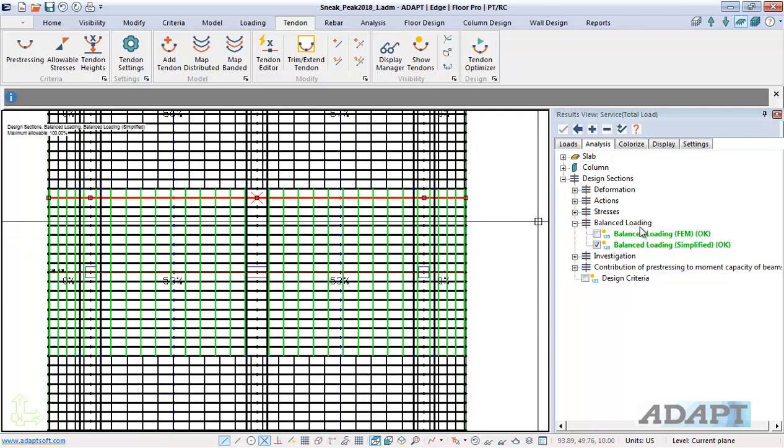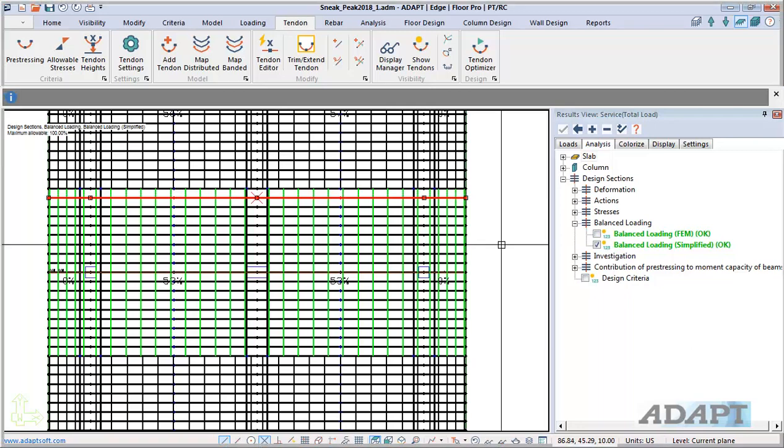The FEM method uses the summation of the pre-stressing vertical components of force within the tributary relative to the nodes, which is tied to the finite element solution, versus just this notion of using an externally removed, let's say, cable and having equivalent loads applied to a structure, which is the uplift that we saw earlier.